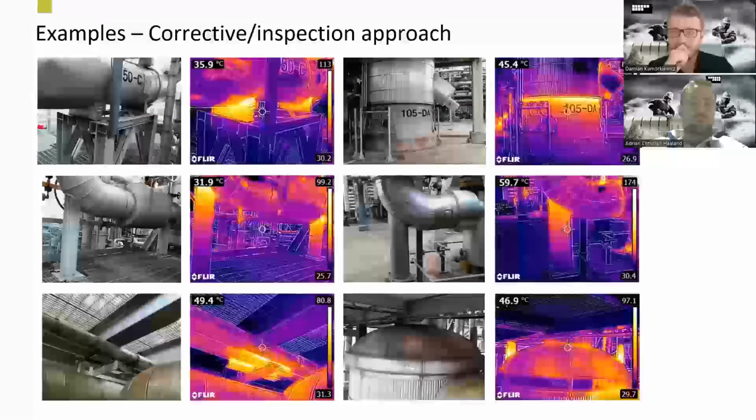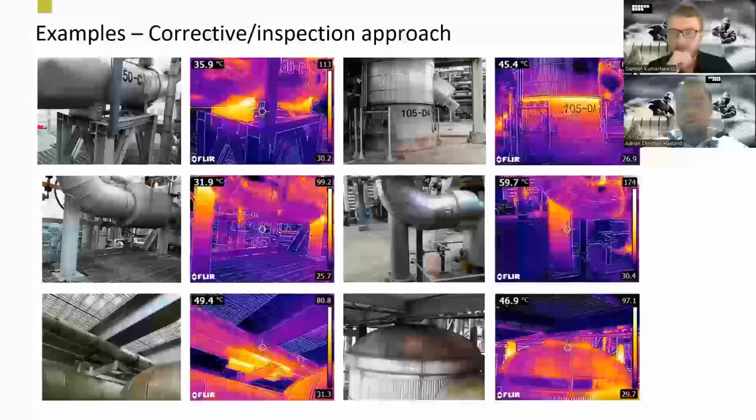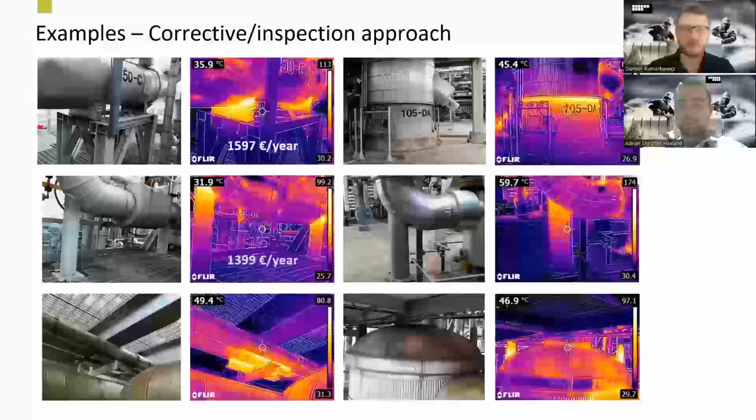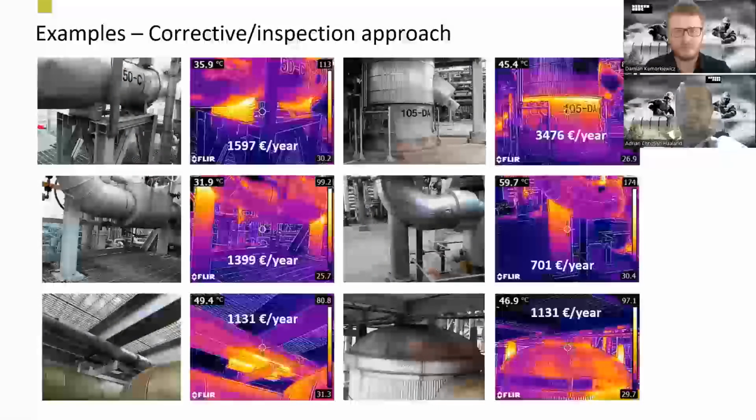But what are the costs of some of these examples today, when we consider today's energy prices? How much does a heat loss for a support or a trunnion or wet insulation cost operators in terms of energy bill, in terms of CO2 quotas, and in terms of electricity consumption? Due to the recent energy prices, cases like these now cost the operators an almost unimaginable amount of money, because this is not a special example. You will find hundreds and thousands of these examples throughout the refinery plant.